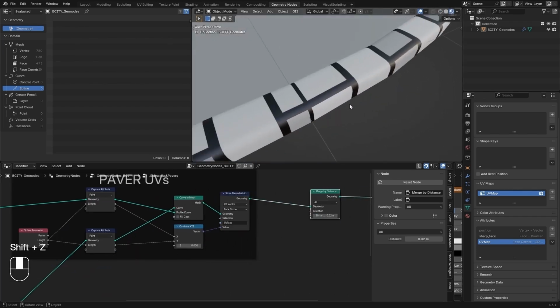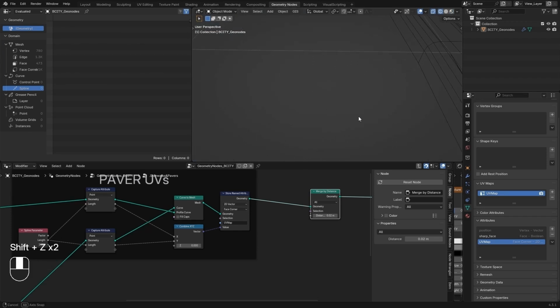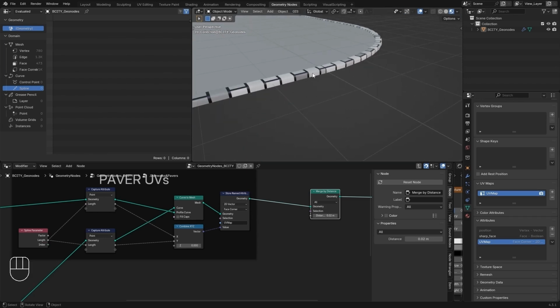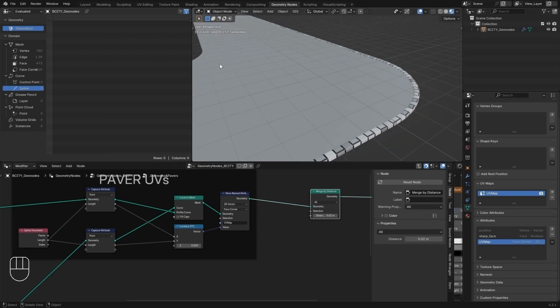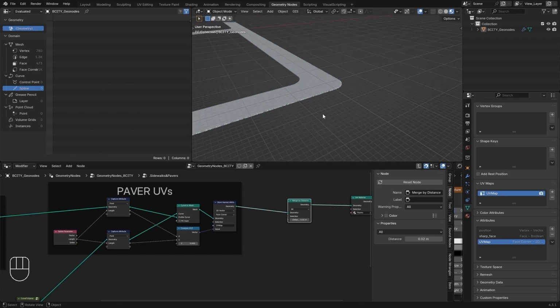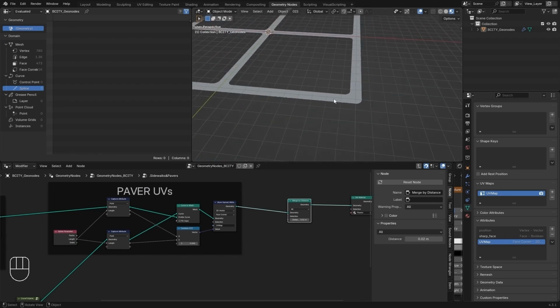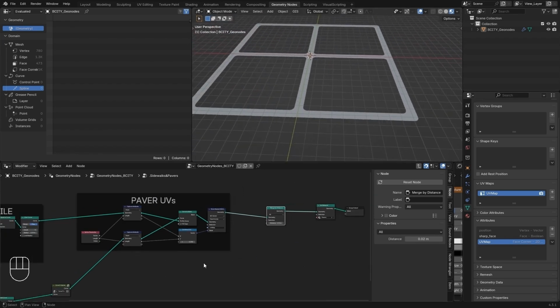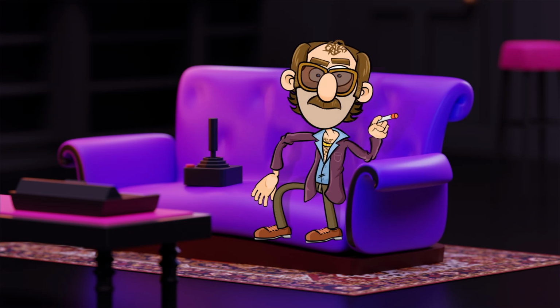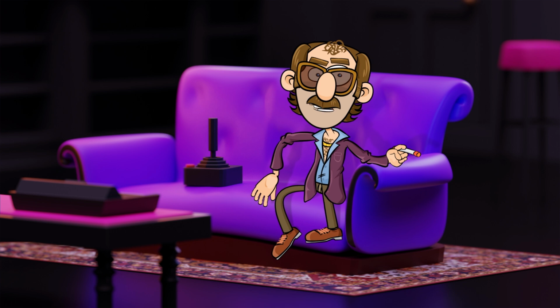How much should we set the distance to? We don't want to break the fillet curve, so let's set it to 0.02, which is half the radius we used earlier. That looks accurate and seems to work well. There is going to be an issue with this later on, when we do the interiors, specifically the interior curb for our sidewalks. But we'll handle that when we get to it.